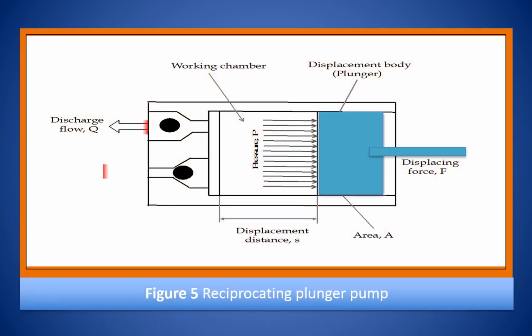This shows a simple schematic diagram of a piston pump with increasing and decreasing cavity during the suction and discharge stroke respectively. The liquid flows into the pump as the cavity on the suction side expands, and the liquid flows out of the discharge as the cavity collapses by the action of the forward and backward moving piston or plunger.